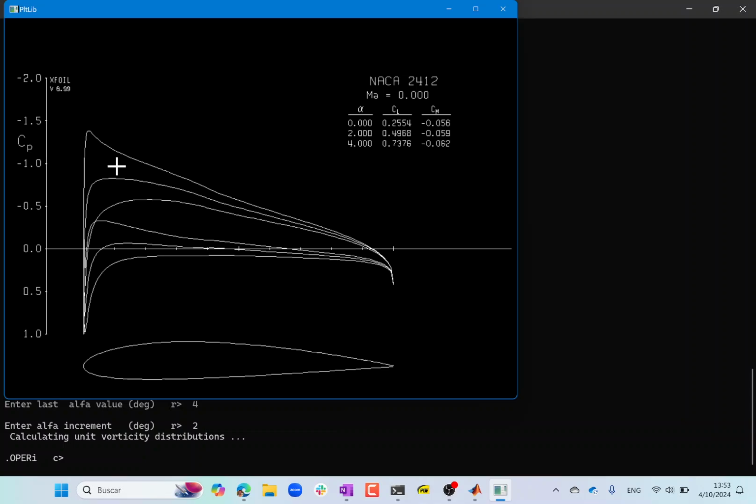Yeah, if you have a very negative angle of attack, you're going to find that making the angle of attack closer to 0 but still negative is going to help move the center of lift closer to the leading edge. Yes? Yeah, I think I have something that fits, but I'm having a bit of trouble understanding the physical